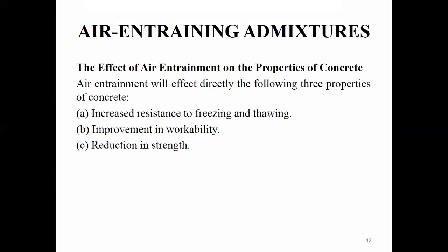Next, what we are going to discuss is strength. Coming to strength, you may see the word reduction as a negative point, because reduction in strength means how can we adopt this concrete. But imagine you are placing concrete in some northern region, where the temperature will be below freezing point.